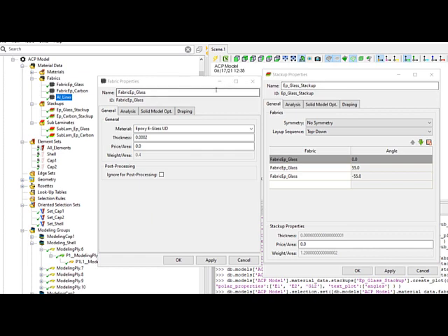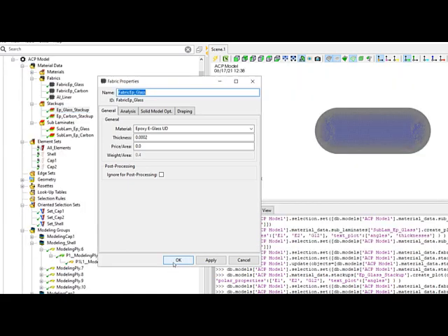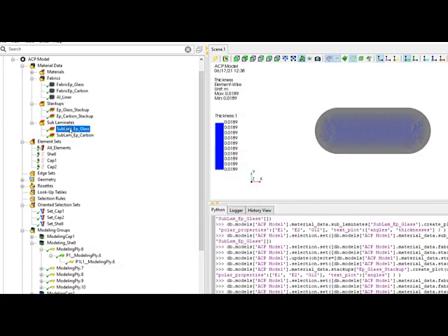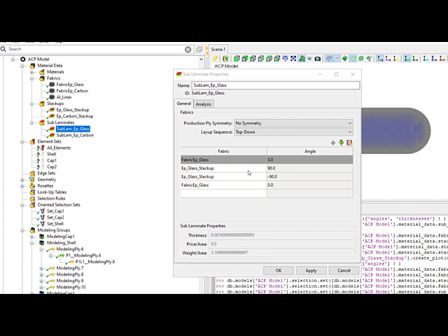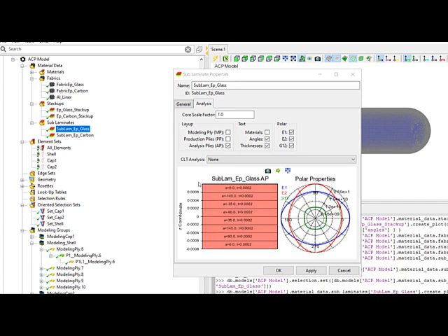For the epoxy glass, we need to define some stack-up properties. These stack-up properties allow us to define, for example, the orientation of different fabrics. When we define this, we can use laminates at the end to define the total thickness of our composite, as you can see it here. We have more or less a ¼ inch of composite.